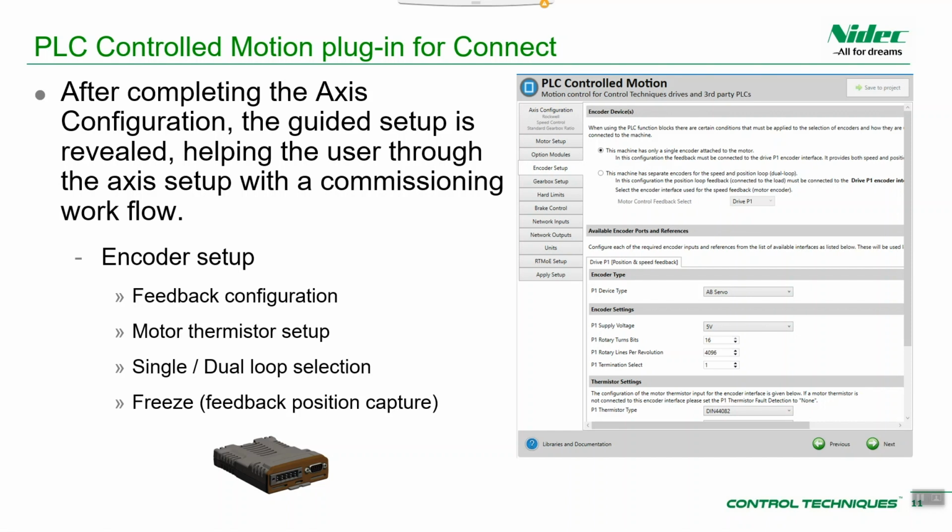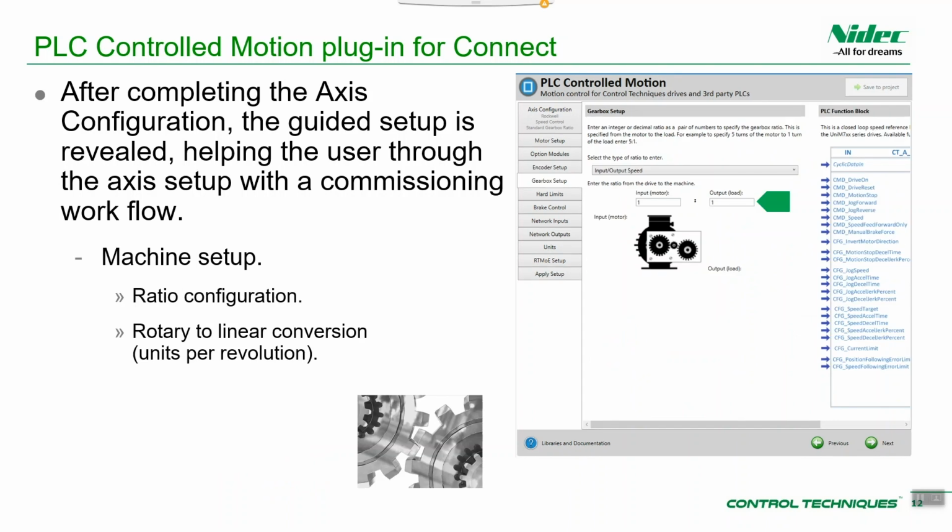Okay, so this is for the AMC motion control type motion interfaces. You don't have this kind of setup for RPM type axis or frequency control type axis. Other things that you've got under here are things like freeze position capture. So if you want to know with high precision the position of the axis, like a custom homing routine or something like that, you've got that capability here, and the configuration for that is in this tab.